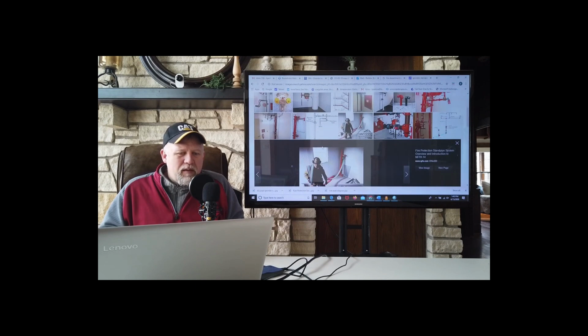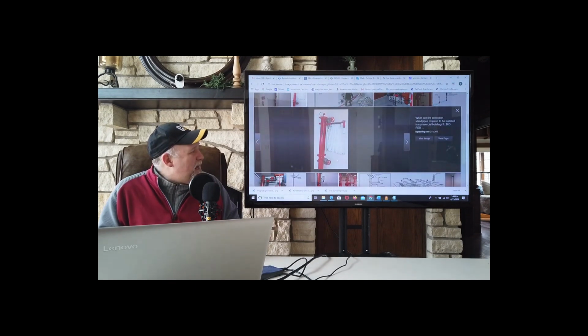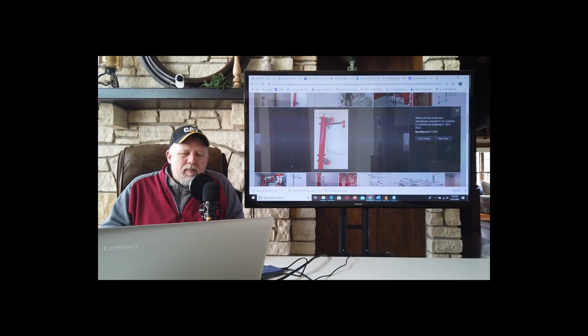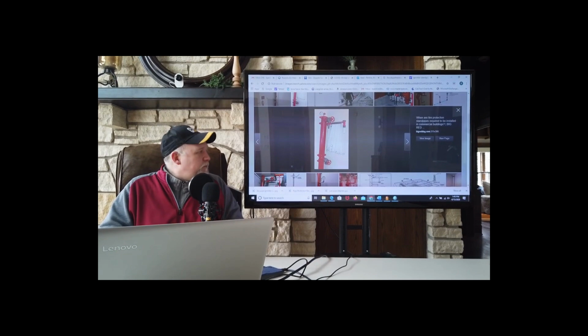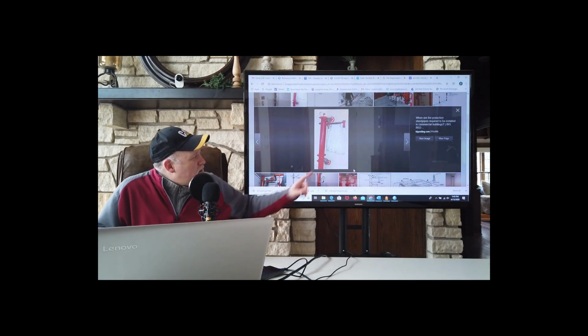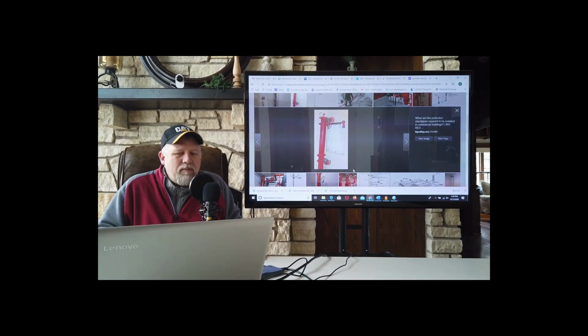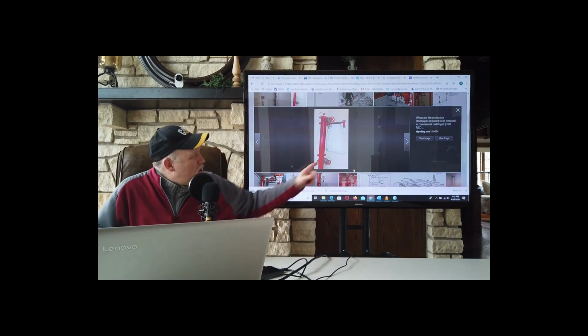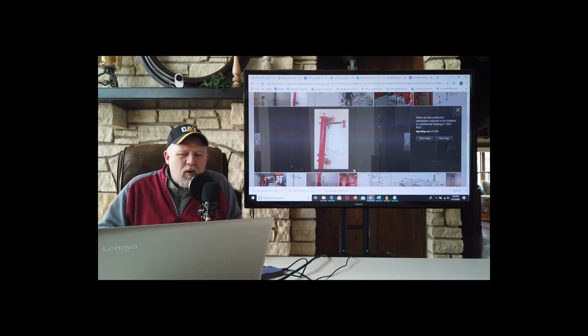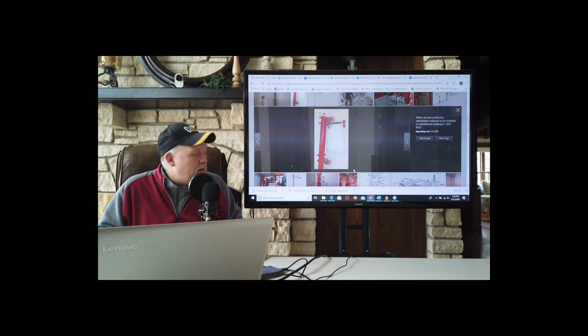Now, in older buildings, you might have seen a standpipe and existing hoses. You're probably not going to see too many of these anymore. Most fire departments have had buildings remove these for a couple of reasons. One, these hoses require maintenance and inspection, and most of the time, as they age, right here where they're folded, they will get holes. So they are worthless. In fact, they're worse than not having anything because now they're in the way.